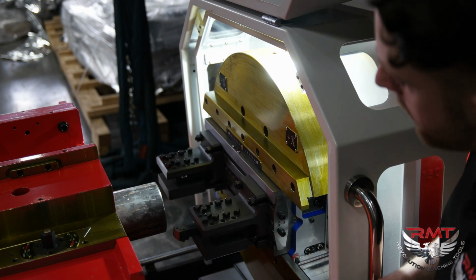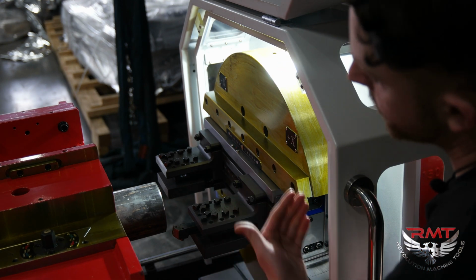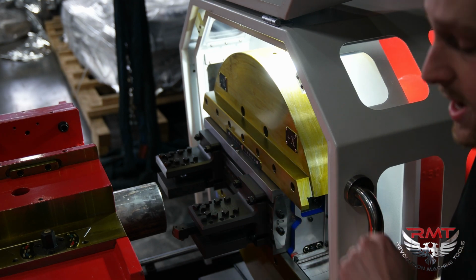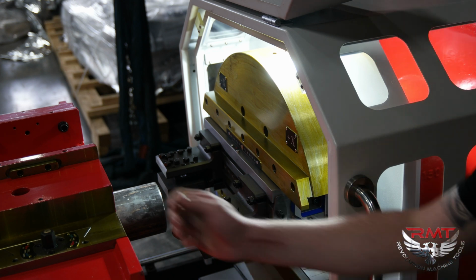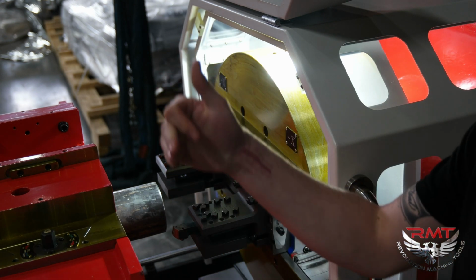So right now I am working with what's going to be my tool 1, and it is on the positive X coordinate, which means for me to go deeper into the part, it's a negative movement in X, whereas if my tool was on my positive X, then it would be a positive X value to go deeper into my part.